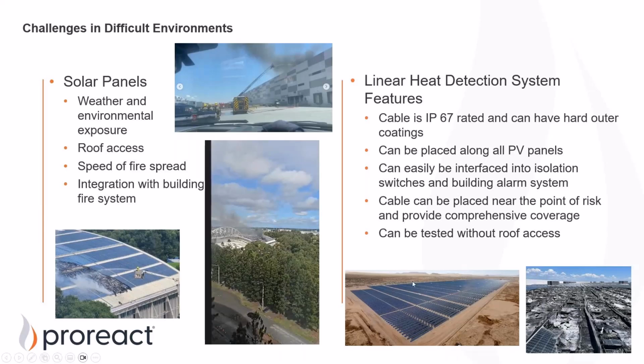Also solar farms, like this one in the bottom right. This one also in Arizona, north of Phoenix, and it is one of a couple different projects that we know about using linear heat detection. Could be a deluge sprinkler setup, or it could be a pre-action type setup.